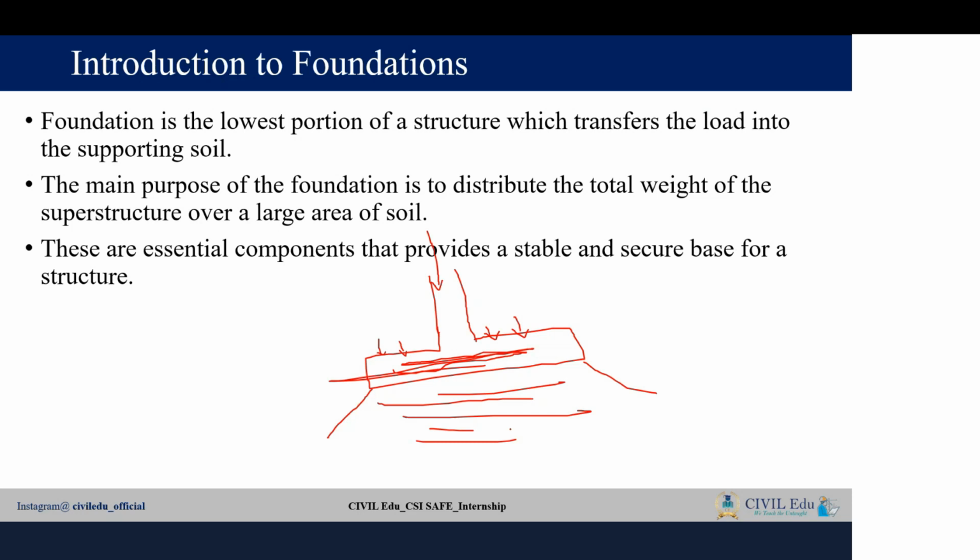You all must have heard the term SBC of soil when you are designing reinforced concrete structures. Whenever you design reinforced concrete structures, especially the foundations, we are going to consider the SBC of soil, which is called the safe bearing capacity of the soil. Now, how will you get the safe bearing capacity of the soil? A geotechnical engineer will give you the SBC value of the soil for your site wherever you are constructing. So it is important to do the geotechnical investigations as well, or you can also call it a soil investigation report, or sometimes just a soil report.